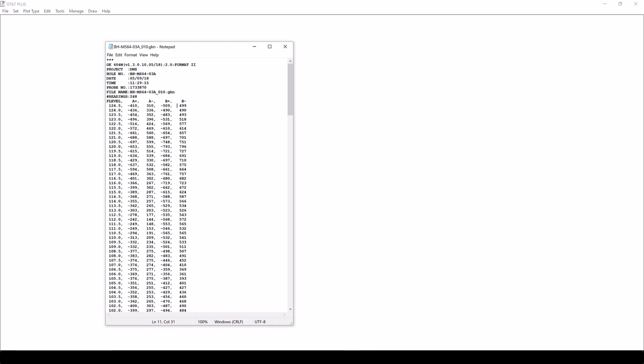The inclination readings are in digital units proportional to the sine of the angle of inclination from the vertical, where 10,000 units represents a 30-degree tilt, or arc sine 0.5. Or you can think of these values as representing 20,000 times the sine of the inclination angle. When you import this file into Gtilt, these exact same numbers will appear in the Gtilt readings editor.